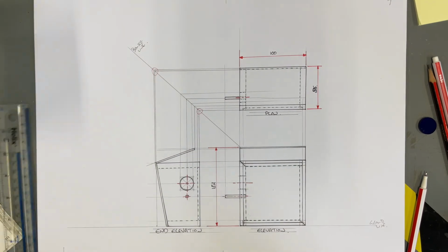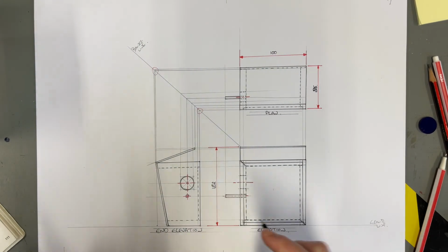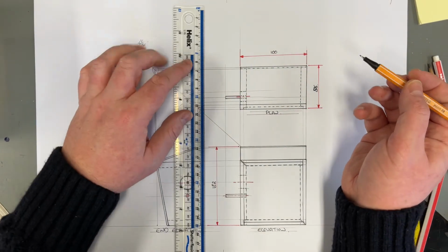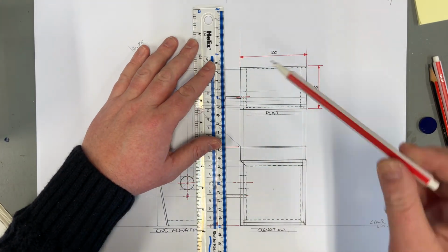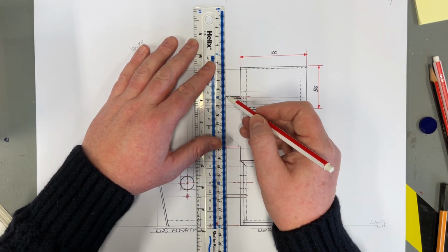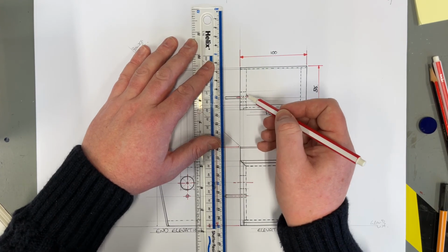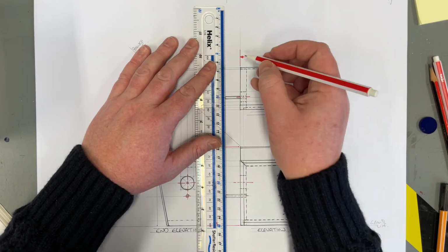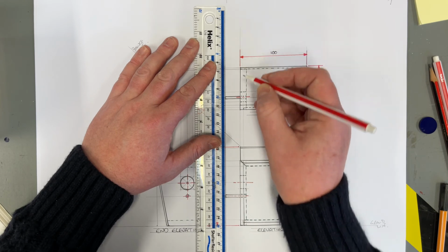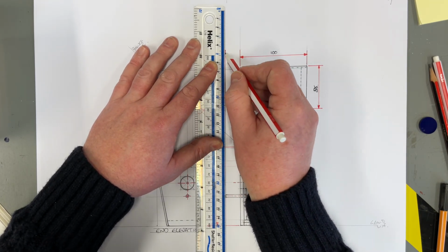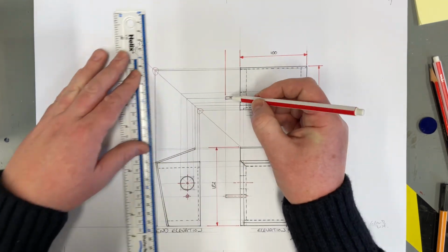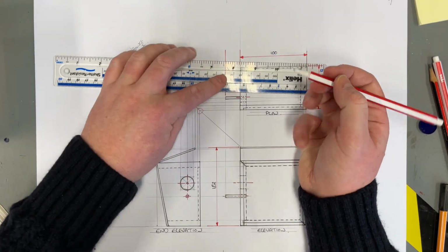Happy enough with that. The other thing that we could do is potentially the perch. We haven't added that size in there. Now, the leader line in this instance, we want to know the distance from here to here, not all the way through. We can use this leader line up here that connects to the back. We'll just extend this leader line up here. Again, it should be a couple of millimeters off of the object itself.